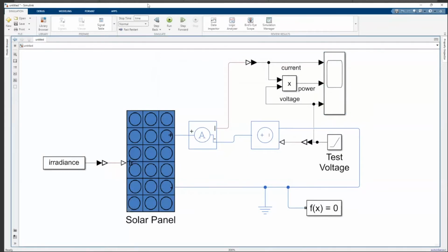Before we do that, I want to explain this. There are 3 modes in Simulink simulations. It's called normal mode, acceleration mode, and rapid acceleration mode. To deploy the apps, we run the models in rapid acceleration and test them. If it works successfully in rapid accelerator mode, then we can deploy them without any errors. So rapid accelerator mode actually creates a rapid accelerator standalone executable from your model.